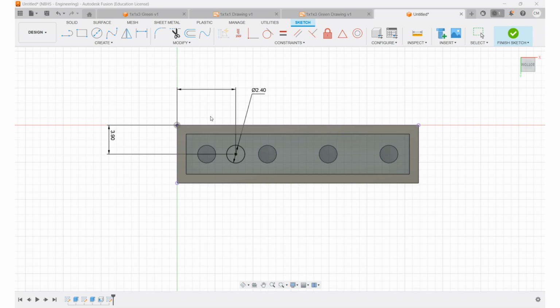I really only need these retention posts or snap rings anytime I have something that's at least 2 studs wide. That's what everything's based on. 2 stud wide is 15.8 millimeters. Half of that is 7.9. And again, this all comes from the property of being able to pick it up and rotate it 90 degrees and it's still all match. All right, so I've got that in.